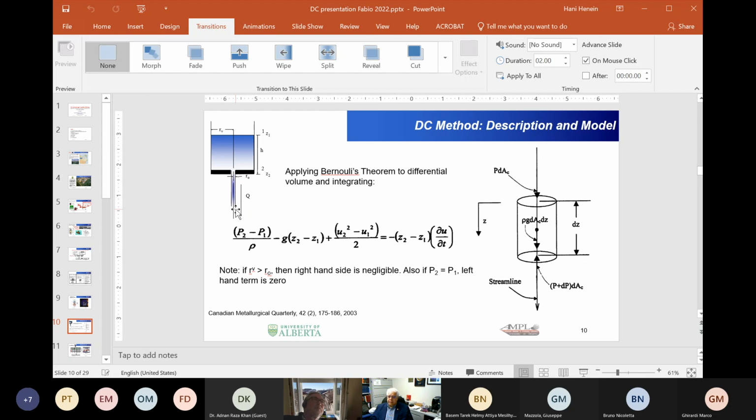If you have no wetting, you can probably do that. But if there is wetting at the orifice, then one would have to add some additional modeling terms, which we're currently working on. It would be a more complicated setup because you'd have to pressurize the top and not the bottom, and it would also be a more complicated model. But I think in theory it should be feasible.